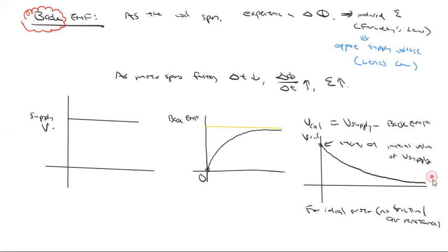The motor is designed to take this amount of voltage and current because that's where it's going to be most of the time, under its operating conditions. You can't design the motor to carry the starting voltage and current, because you'd need to make the motor heavier and less efficient. So if you design it for the operating situation, at the start it can't really take that and might burn out. That's why you need a starting resistor.